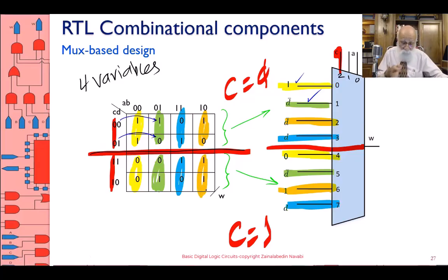Okay. So continuing, now I'm looking at the 1, 0 column, the orange column, or column number 2. That becomes 1, 0. That means D bar. And finally, column number 3 of the upper map, 0, 1 is the same as D, and therefore D goes here. For the lower map, I have 0, I have D bar, I have 1, all ones, and I have D, and therefore 0, D bar, all ones, and D go there.